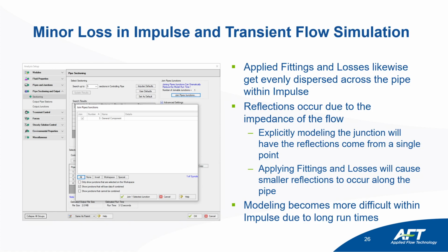We say build it with as much detail as possible, and if the runtime is unagreeable with you, over hours long, then you can start simplifying it, because ultimately what you're trying to see is the pressure surge relation, not the hydraulics of the pressure drops. You're trying to see how that wave is moving through your system.